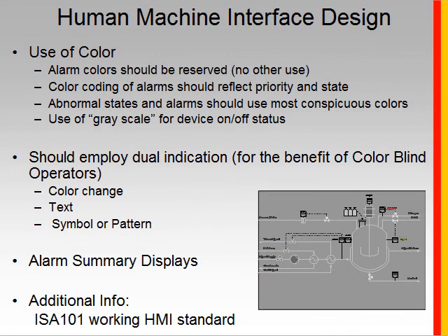Again, you also want to use the most conspicuous colors possible for getting the operator's attention. Alarm summary displays are another key tool that the operator uses to manage alarms. The standard provides a lot of requirements and recommendations on what functions and features should be in those screens. A lot of them pertain to the supplier and what they must provide. But there's also a lot of recommendations on how to set it up to make those work the best.